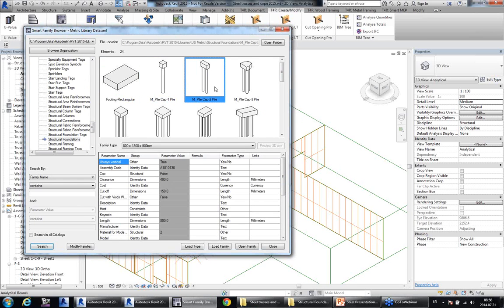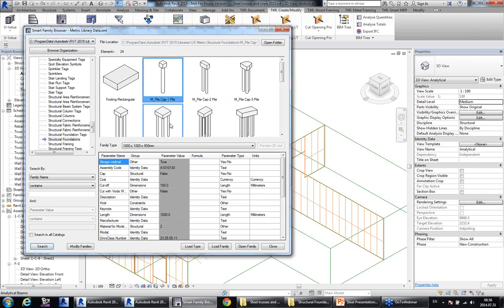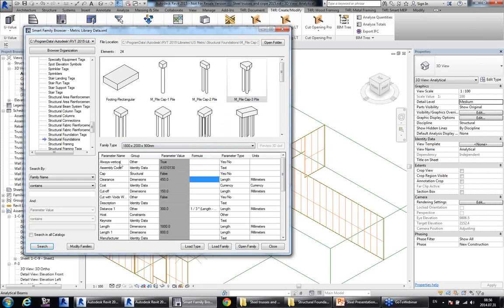Yeah, so now the tool shows me my regular Revit library. You can actually have several libraries that point to different computer or server locations. You can have your library somewhere on the network as a company library. And then here we can check all those types that are created for every family. Then we can check parameter names and parameter values. Then the formulas that were created for the family.